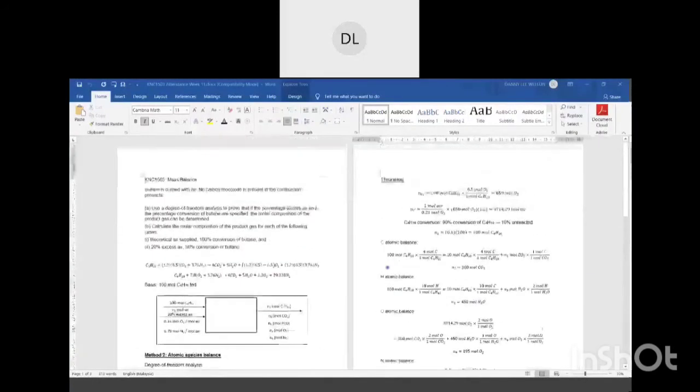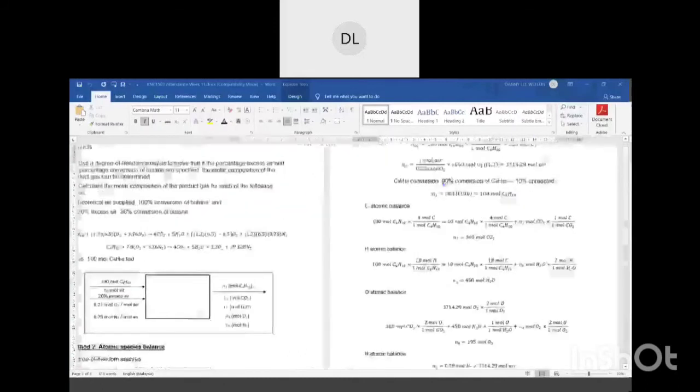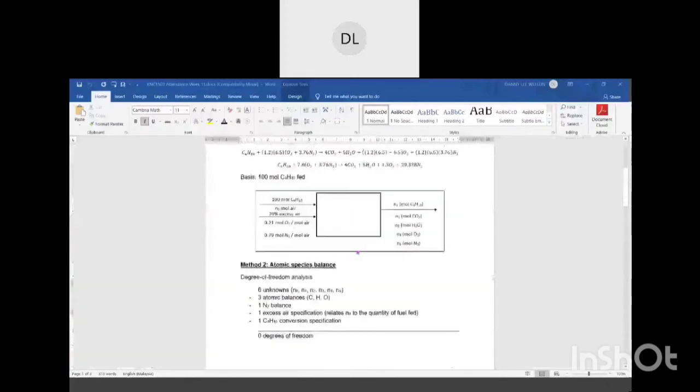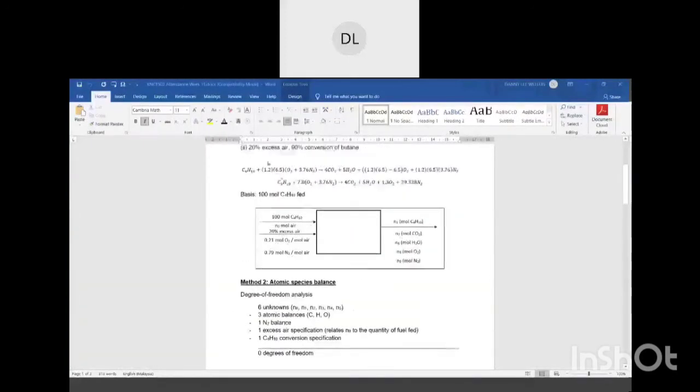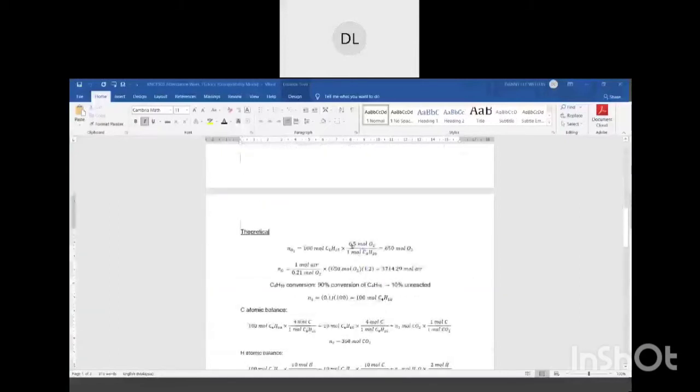First we calculate oxygen. The number of mole of oxygen, which we use 100 mole butane times 6.5 moles of oxygen, which you can see from here, 6.5, which is after you've done the balance, over 1 mole of butane, you get 650 mole oxygen.